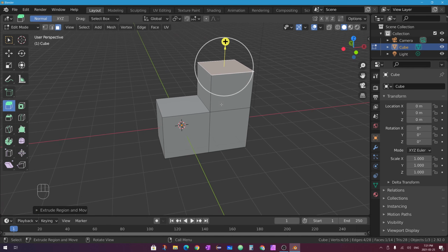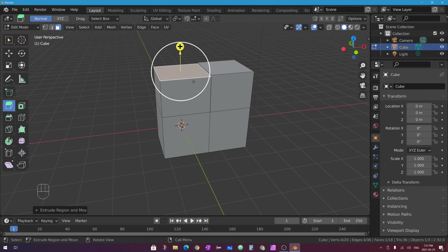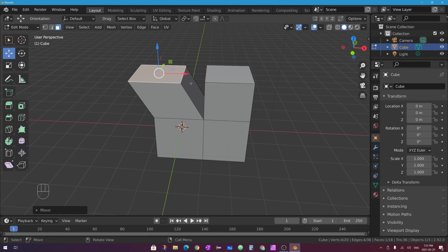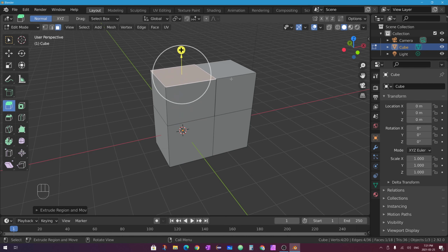And you will notice that if I grab a face that already has a wall next to it and I pull that face up, well, we now have a little bit of messy geometry, because if I now just use the move tool and move this face over, well, I have facing walls that were inside of the middle of my mesh. If I press Ctrl Z a few times to undo, and I use the Extrude tool again to go back up, if I want just a 2 by 2 by 1 block, well, I don't exactly have that, do I? Because I have internal walls. I have internal geometry, and that's not ideal.